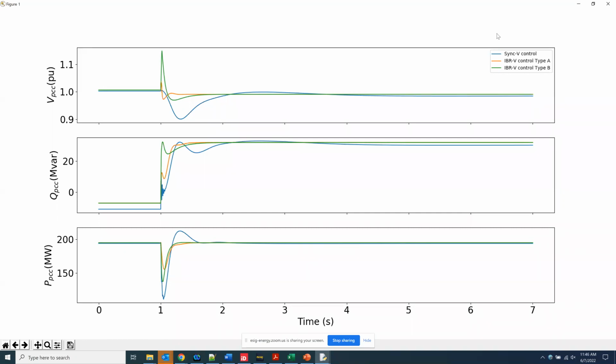We have done some black start studies with PLL inverters, and the PLL is critically part of the synchronization loop. It comes down to how you handle the auxiliary load that's there in the plant. It comes down to how you handle the frequency response control loop. So there is an element of tuning involved there. And as I said, the aim here is not to say that a PLL-based inverter will be able to do everything, and we only want PLL-based inverters. We definitely want all types of control to come into the system.